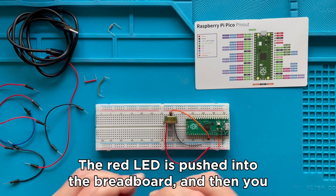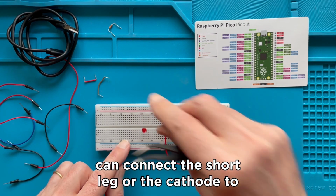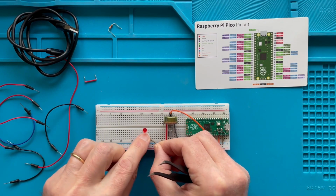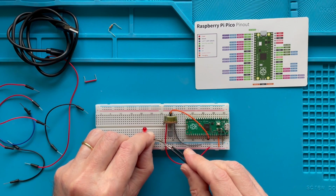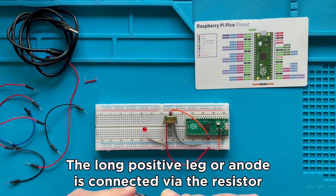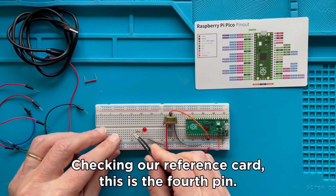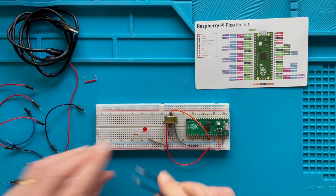The red LED is pushed into the breadboard, and then you can connect the short leg or the cathode to the negative rail. The long positive leg or anode is connected via the resistor to GPIO 2. Checking our reference card, this is the 4th pin.